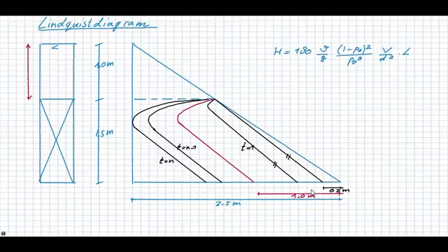Therefore, we normally construct an overflow downstream of the filter, at a height equal to, or higher than, the top of the filter bed. In this way, the maximum available pressure drop is equal to the maximum supernatant water level. When this level is reached, the filter has to be backwashed.